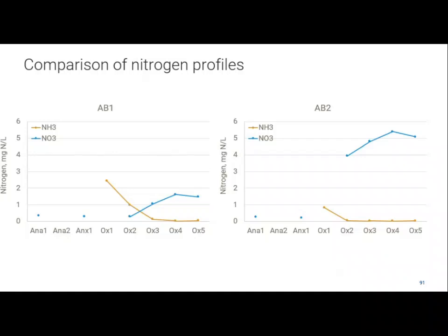But look how low that is, right? This is saying that your effluent nitrate is only going to be 1 or 2 milligrams per liter, maybe like 5 or 6 milligrams per liter. What's going to happen to the RAS in that clarifier blanket if there's only 6 milligrams per liter of nitrate in your mixed liquor? What's that? Yeah, it's going to go anaerobic in the blanket. Right, so you've got to really be managing that blanket then and thinking about how long the blanket's sitting in there and trying to get it out. The lower the nitrate, the less flexibility you have in building up a sludge blanket.